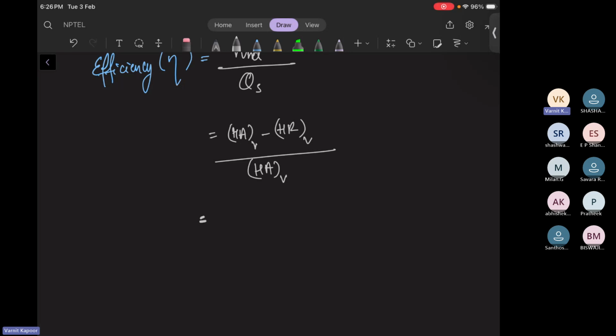So it is basically for a constant volume process. Why am I saying this? In the last tutorial I also explained, from the first law of thermodynamics, dq is equal to du plus dw, and dw is nothing but pdv. For a constant volume process your heat is getting added, these are heat addition at constant volume and heat rejection at constant volume. When your volume is constant, this is 0. So dq is nothing but cv dt. So net heat addition or rejection, whatever the interaction is, is a function of temperature only. That is why I'm writing like this.